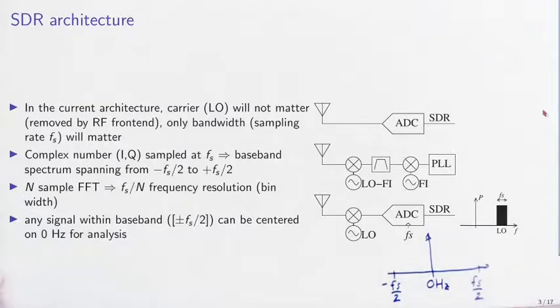And the discussion of today's tutorial lies in the fact that multiple channels or multiple spectral components might be found within this bandwidth. So our objective will be to try to process each one of these spectral components simultaneously in parallel, by bringing each one of these components centered on 0 Hz, centered on DC.